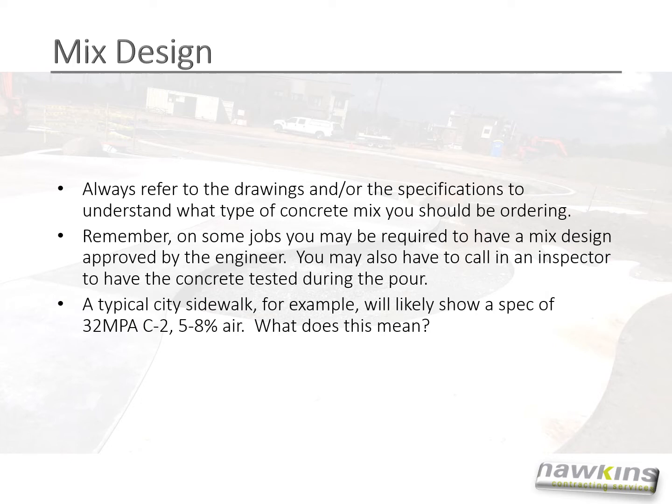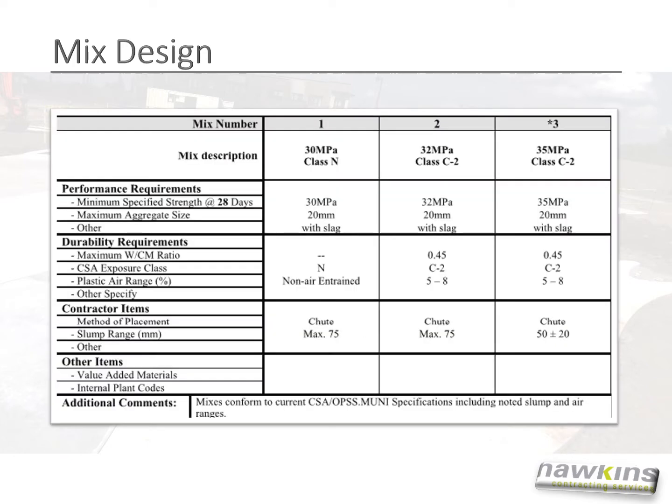A typical city sidewalk, for example, will likely show a spec of 32 MPa, C-2, 5 to 8% air. What does this mean? This means you're ordering mixed design 2.